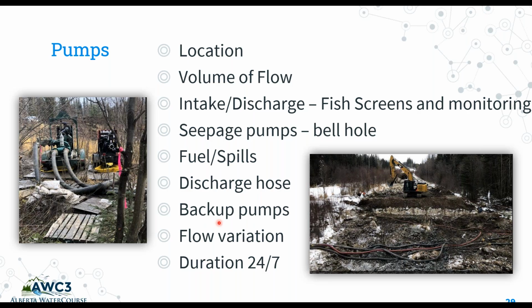Flow variations. You could see a rainstorm, or if you're working in late fall and it snows, it gets warm during the day. So you want to understand that your pumps are capable of handling the volume, and also the duration. So if you're working on a smaller crossing, you may use some 4-inch gas pumps, and your planned excavation and restoration will be less than a day. Or are you dealing with large pumps, 8-inch diesel pumps, 6-inch diesel pumps that are going to be pumping around an excavation for a larger period of time?